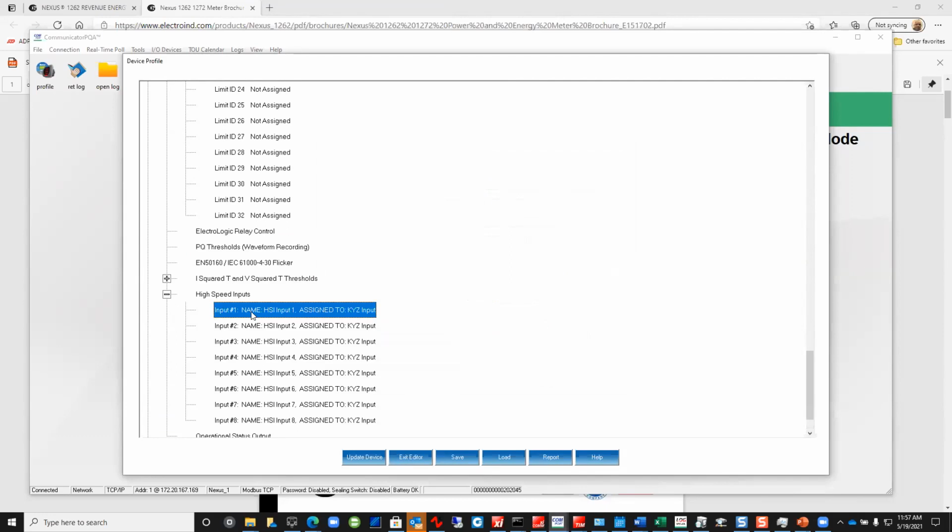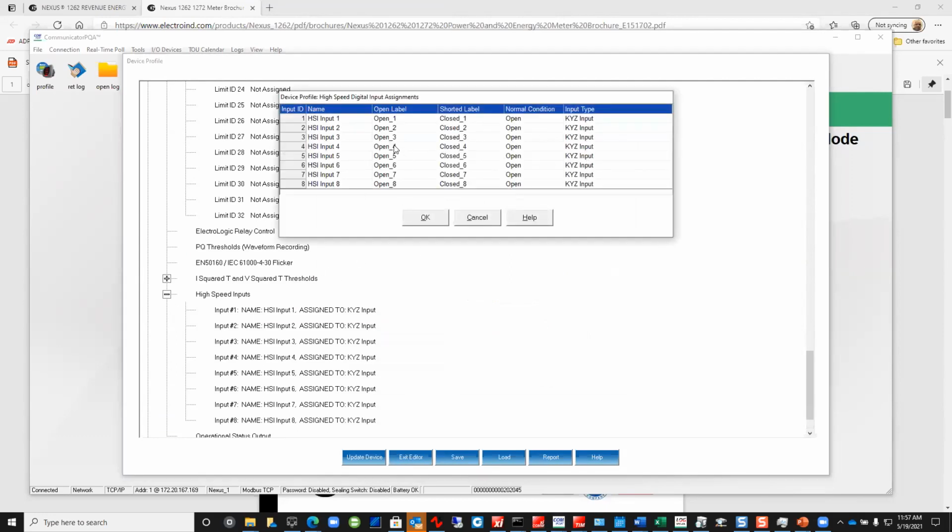So yeah, this is where it is. Here is where we have our 8 inputs, and you have the option to choose waveform trigger or make those changes. I would think this would have been placed further up in the order of programming, but it follows afterwards. So if I wanted a waveform PQ trigger on input 1, I would be able to select it from there.